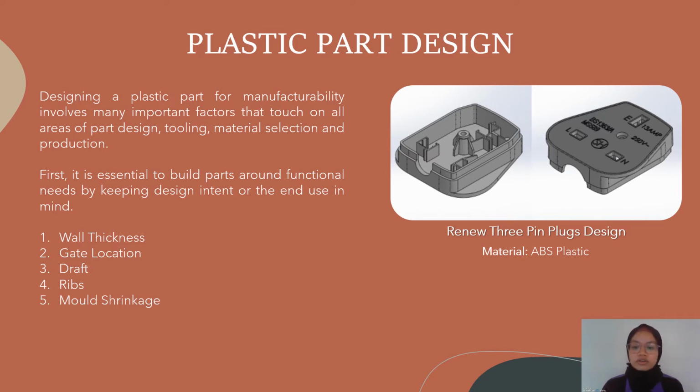Second, the gate location. Gates are critical to ensuring the resin flows properly into the mold. These small components of our design are what direct the flow of resin from the runners to then be distributed through the part. Type of gate and placement has an important impact on the part's overall quality and reliability.